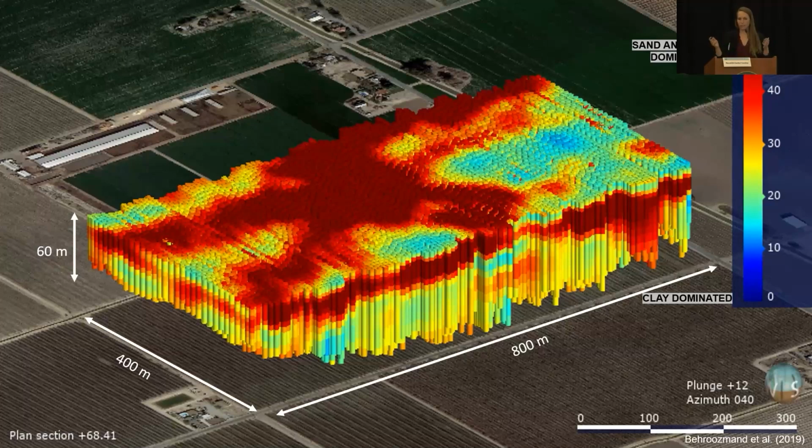You could look at two different sites. One looks much more resistive than the other. Maybe that's all the information you need. But there are instances where you're going to be interested in these intermediate resistivity values, the light blues and greens. And because of that complication in what is influencing resistivity, you've got the sediment type, you've got the water content and the water quality, it can be difficult to understand exactly what's going on in these areas.